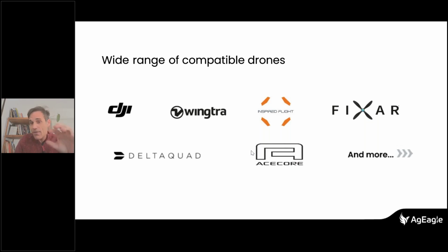They have a very, very good integration with our camera, with their autopilot system, and their own post-processing software can seamlessly process multispectral maps. The only thing is Wingtra does not have a DLS on the drone, right? So maybe we can talk about that as well, about the calibration. We have the DLS on one side, we have the calibration panel on the other side.